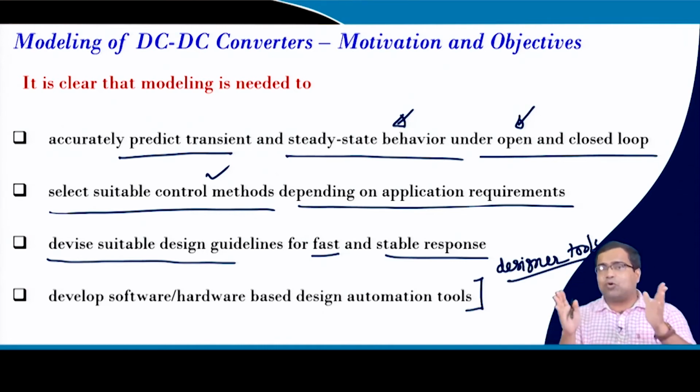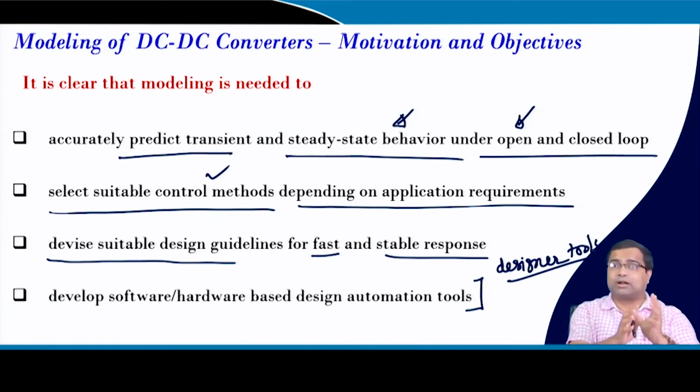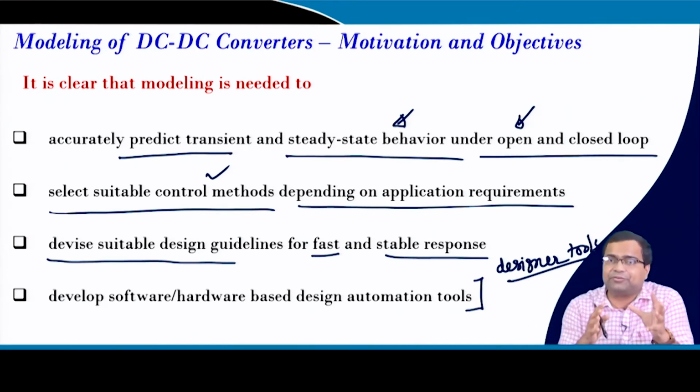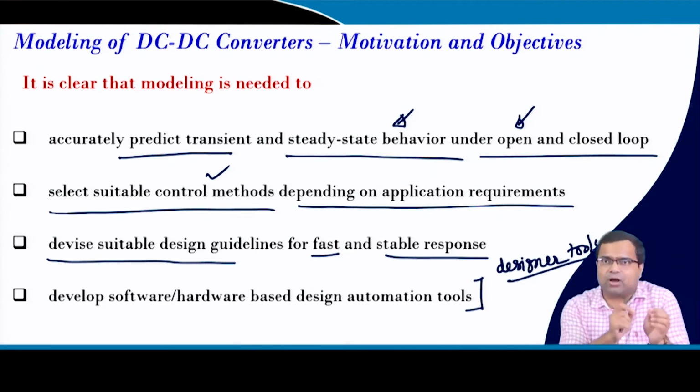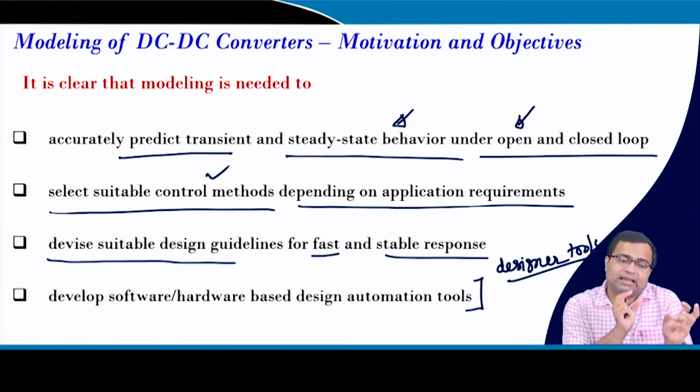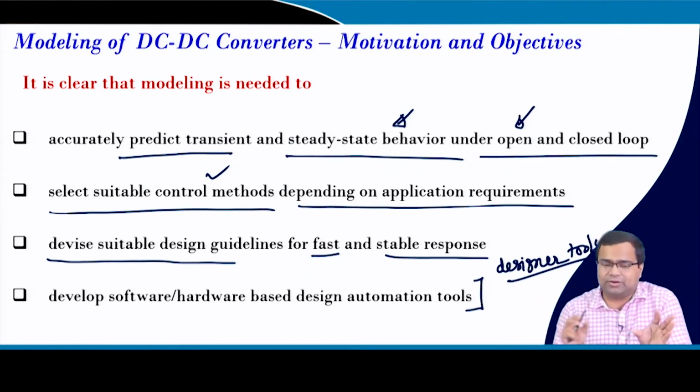Then it will try to correlate, across different industries, what their existing products are that are close to that, and what the range of products is that can meet certain input output voltage and load specifications. Then it will give you different variants. You have, like, IC number 1, IC number 2, which can meet all these specifications, but each of them has a certain bill of material.